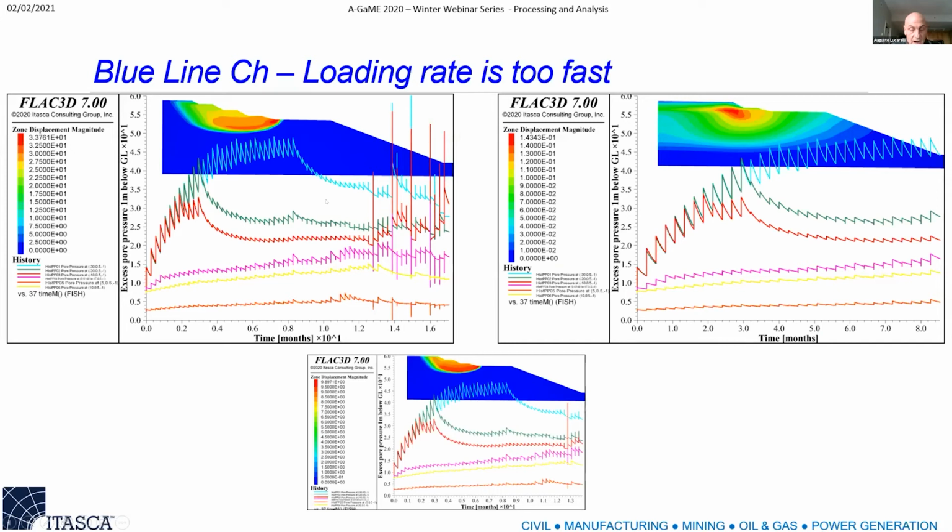All these analyses are done in drained condition. There is no undrained shear strength in any way, shape, or form. It's the interaction between the skeleton and the fluid that determines, through the volumetric property of the water, the pore pressure generation during construction.